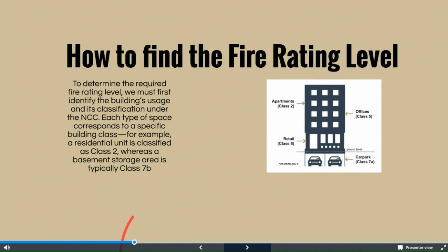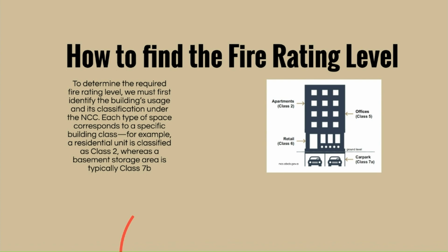Finding the fire rating level is a bit complicated, and I'm trying to give you the sense in a simple way. What you need to do is check the building classification, and each space classification can help you to find the fire rating level in BCA.